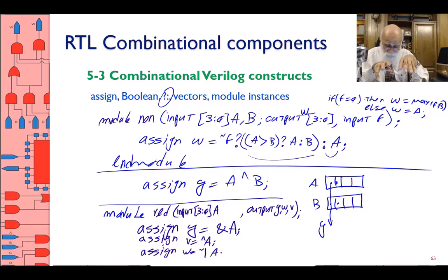And then you have the curly bracket. Curly bracket concatenates two things together. So what if I have B as another 4-bit vector? What I want to do is have A and B concatenated together and do the reduction on the concatenation of A and B. So this curly bracket, A comma B, forms an 8-bit vector, and reduction is done over that 8-bit vector.